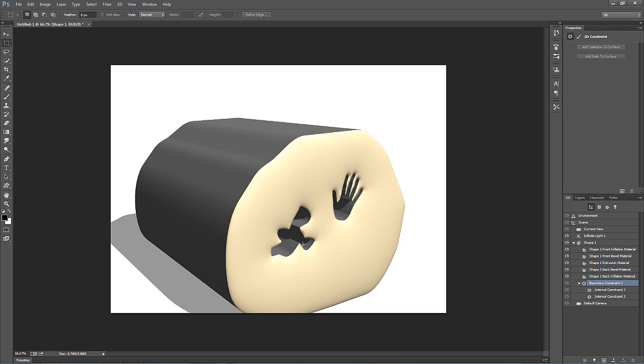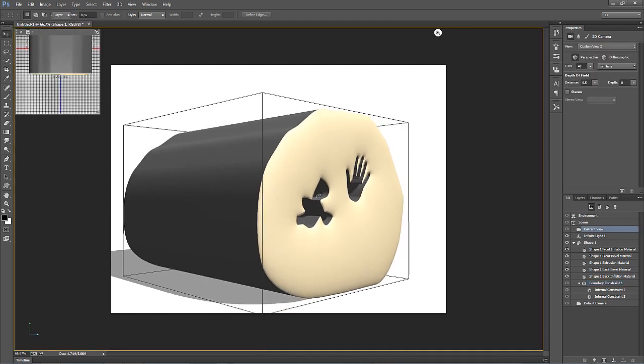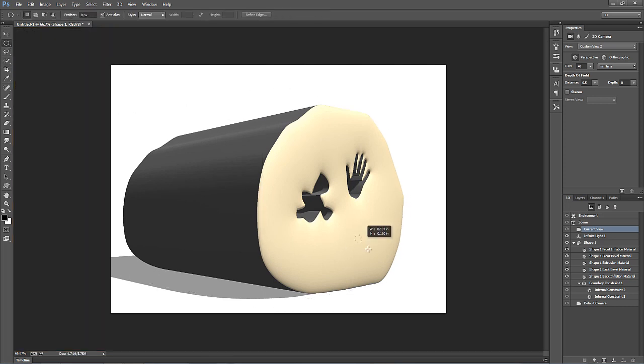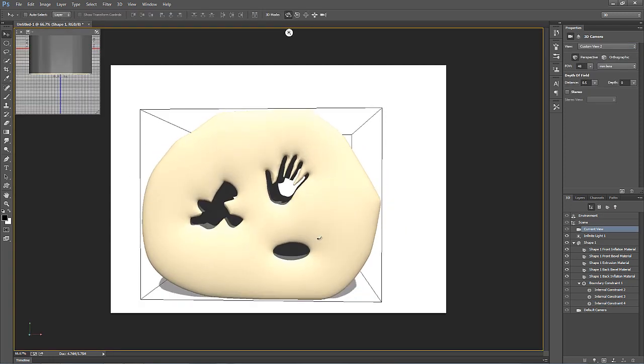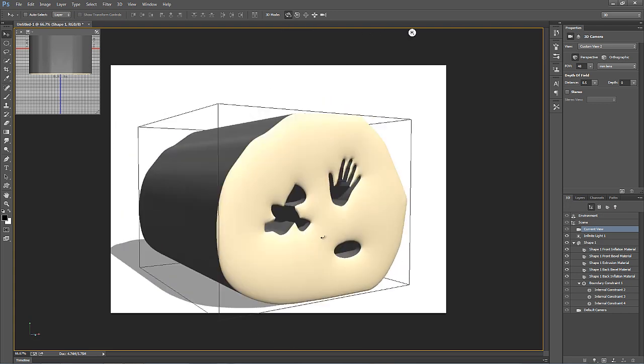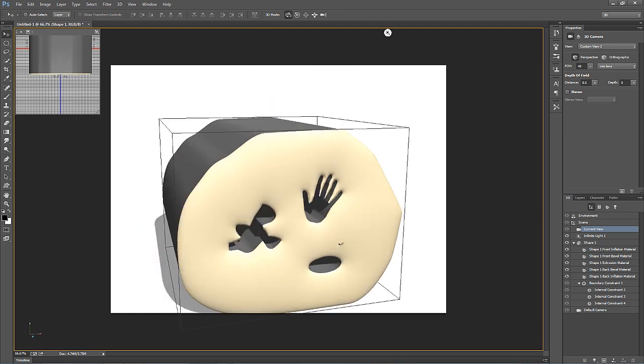Bummer, right? So you consider, what if I turn it at an angle? What if I have a very strict angle here and sort of get an angle in there on it? Let's see what that does. Oh, well, we get a little imprint there. And if we change that to hole, look what happens there. It goes straight through just like the rest of them do. So you can't even get the angle to work properly. It still puts it as perpendicular to the surface of that extruded area.